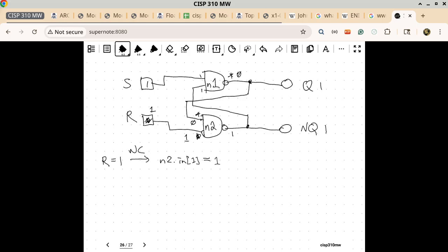Okay, thank you. So since we did change one of the inputs of the gate, we have to give it a little bit of time, propagation delay, and then we ask, after a propagation delay, are we looking at any changes to the output for N2? N1 is not a problem because none of the inputs of N1 is changing. So we only have to ask, what about N2?